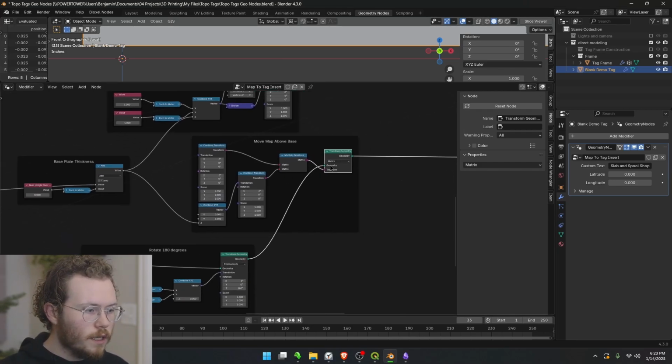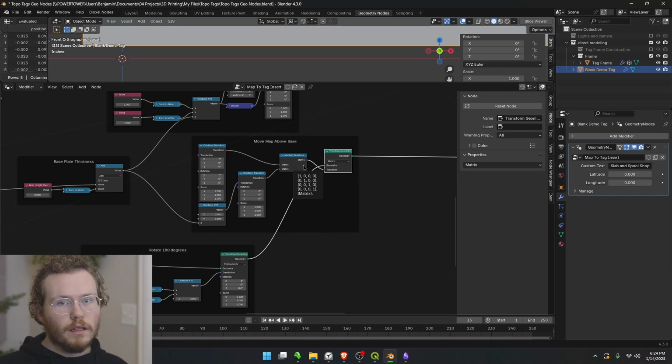So we just offset it by that much so that when we're trying to cut the letters out of the bottom of the map, we're not cutting them out of the map data from QGIS. It's just really dense, and that would end up taking a lot longer. So we're doing a proxy step where we're cutting the text out of the base layer and then connecting the base layer to the bottom of the map later.